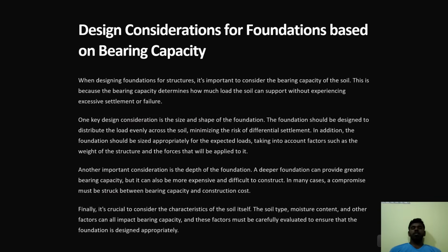Design considerations of foundation based on bearing capacity. When designing foundations for structures, it's important to consider the bearing capacity of the soil. Bearing capacity determines how much load the soil can support without experiencing excessive settlement or failure. One key design consideration is the size and shape of the foundation. The foundation should be designed to distribute the load evenly across the soil, minimizing the risk of differential settlement.